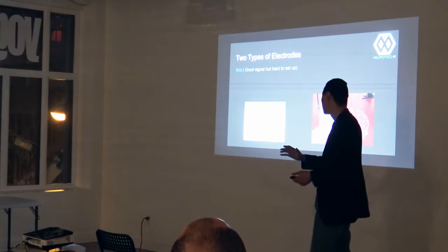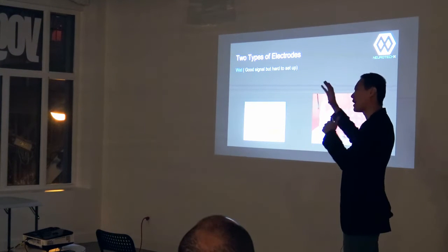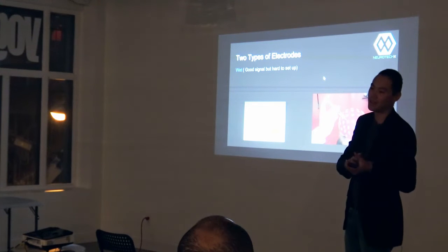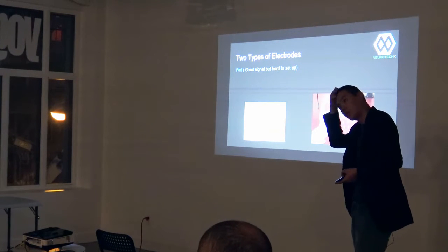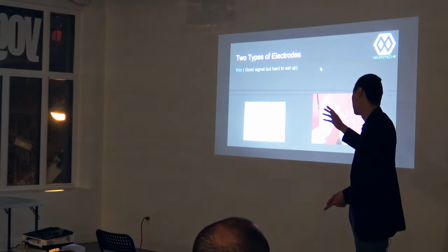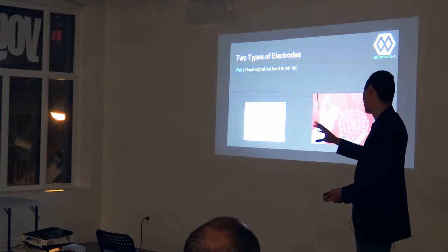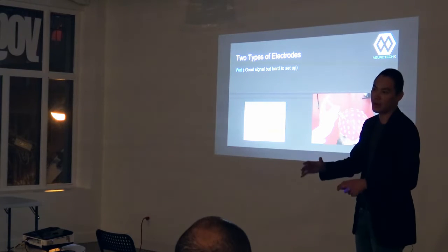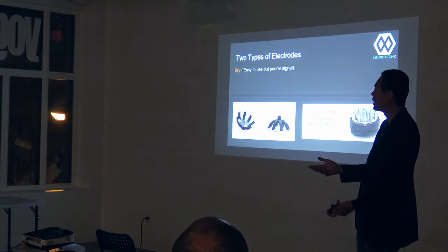So the fundamental differences between EEGs right now are whether they're wet electrode EEGs. Well, keep in mind, I misspoke. Right now, there are two types of electrodes. There are wet-based electrodes where you need a gel to create conductivity on the surface of the scalp, because if there's not enough conductivity, the signal will not be strong enough to be of any use. That's one approach. It's really nice and has a good signal, but it takes a lot of time to squirt the liquid in there to get a good signal. It's not very economically viable if you're running research en masse. You need a whole whack of data, so it's important to have a quicker, easier way to scan people and get relatively similar data.